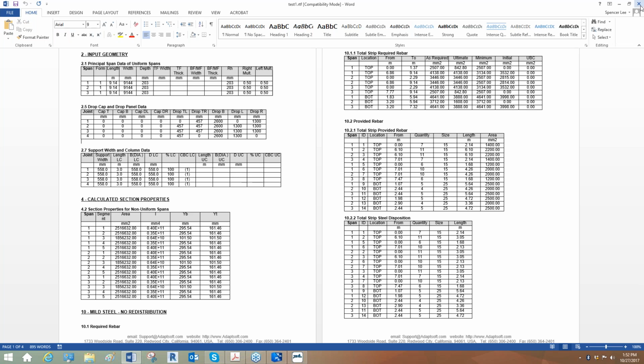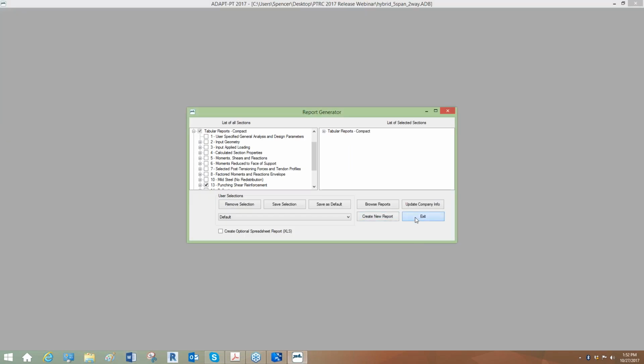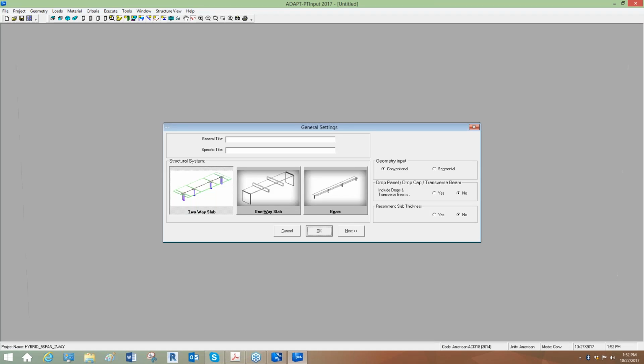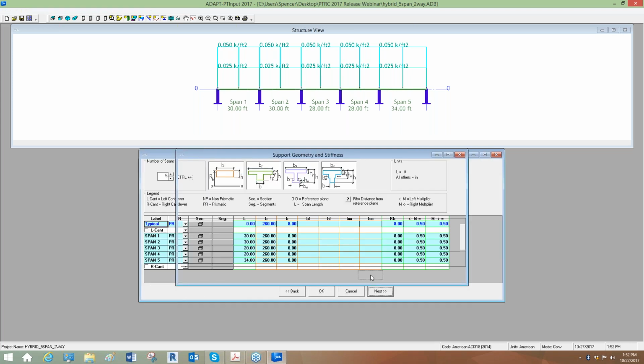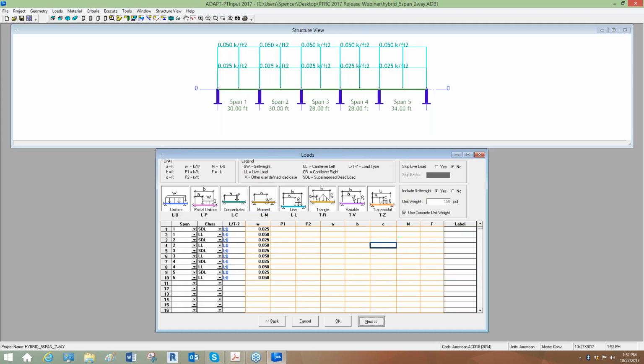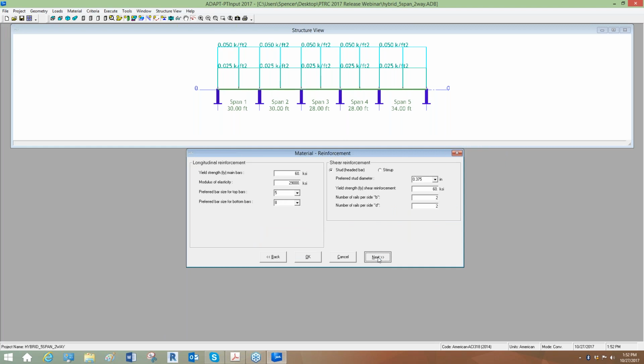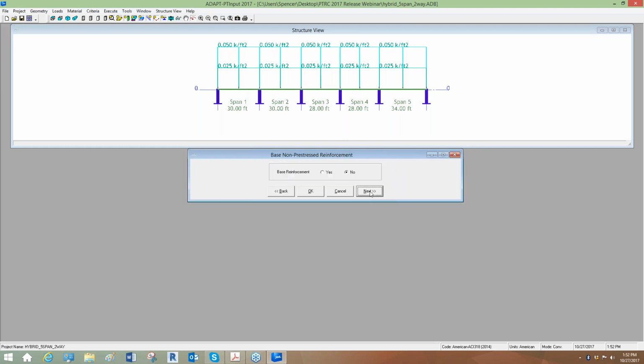Honestly, I don't have a great gauge on how many people use the rebar curtailment option, but what it does is it bypasses the hard-coded way that the program arranges reinforcement. So this was introduced in version 2015. And in previous versions of the software, the curtailment was not there. There was no dialog menu for it.